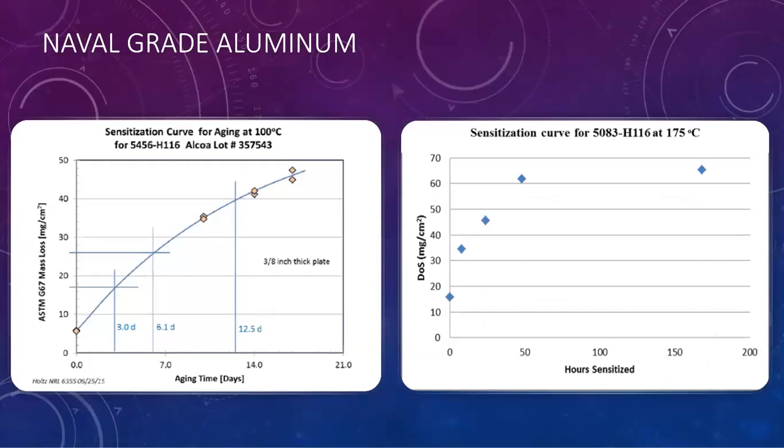So they can test this and figure out the amount of beta phase that has formed with a destructive test called nitric acid mass loss test, in which they take a chunk of the wall and dissolve it in nitric acid and see how much mass that it loses. Because if you think about taking tiny specks of a brick wall, you're not going to lose that much mass. But if you're dissolving that whole grain boundary, you lose a whole grain. That's a lot more mass loss.